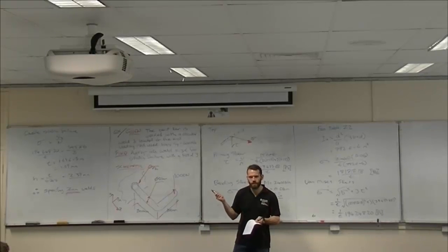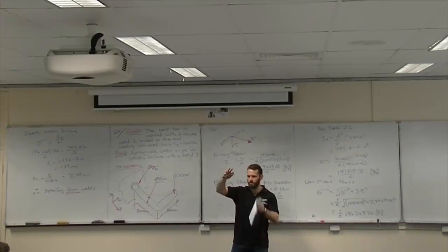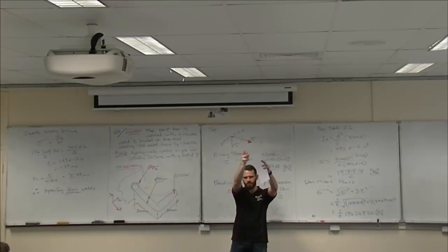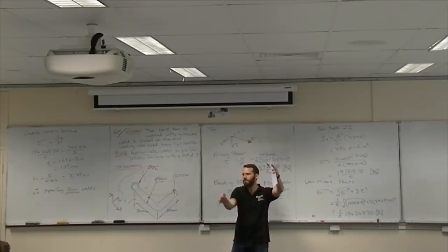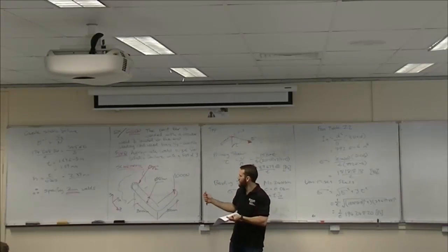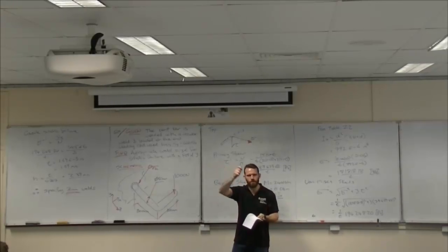So torsion, where's that maximum for a circle? Whole perimeter. Yeah. Shear, we're saying that for welds the shear is even everywhere. We don't have that profile where it's max in the middle and minimum on top and bottom because we don't have the whole profile. We don't have the whole continuum for it to distribute properly. It's just a narrow weld. The only way it can distribute is to distribute evenly, which is mostly accurate. So torsion and our primary and our secondary shear are even everywhere.